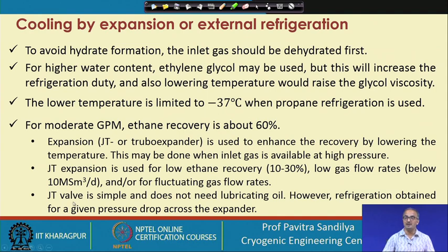And one more advantage is this: the JT valve is simple and does not need any lubricating oil, which is needed by any kind of moving or rotating machinery. However, the refrigeration obtained for a given pressure drop across the expander is less. So, we get a smaller amount of refrigeration for a given pressure drop when we are using the JT valve.